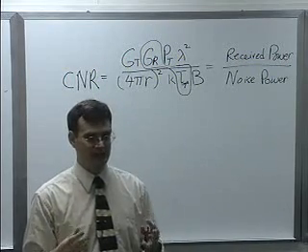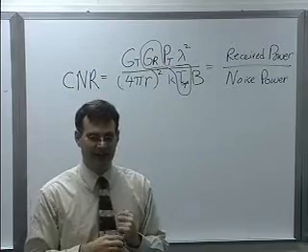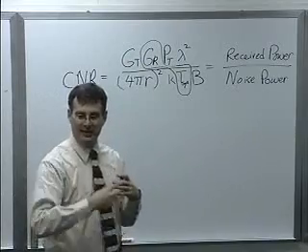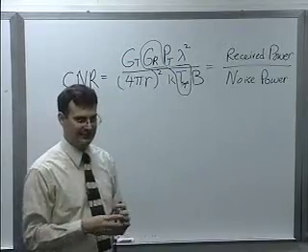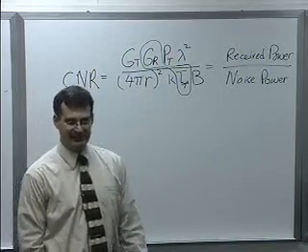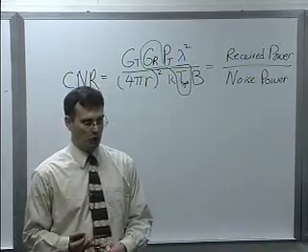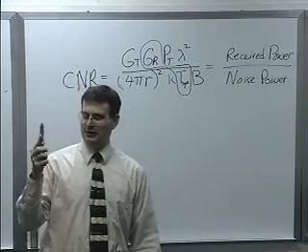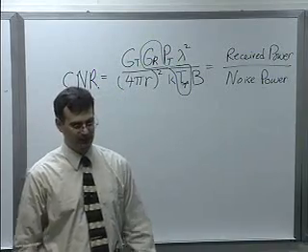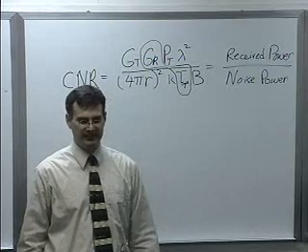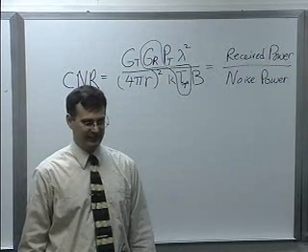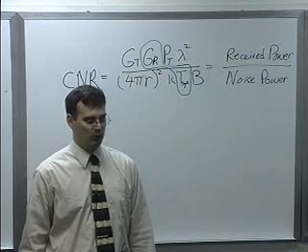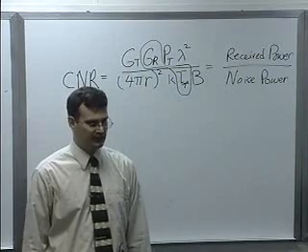And that'll be a really nice metric, because the higher that gets, the more sensitive the receiver is and the longer distance you can make your link, and the better the decoding will be if it's a digital link. So when you talk about the G over T of a cell phone, you'll be lucky to get like 1/100th out of this thing, because the receiver antenna gain is probably about 0 dBi. It's pretty crummy. You'll be lucky to get isotropic gain on average out of this thing. And then the receiver sensitivity is pretty low. It's going to be like 200 Kelvin. So what is that? 0.005 G over T. Terrible.